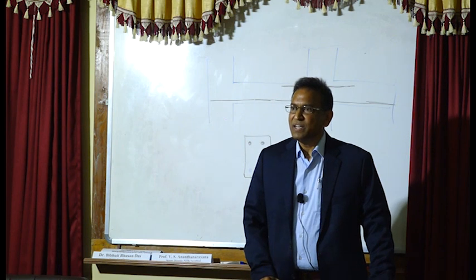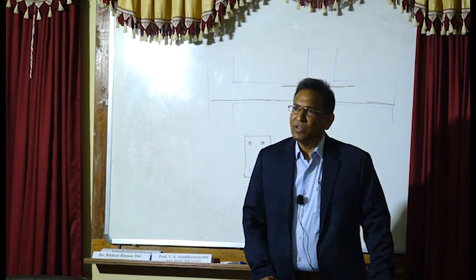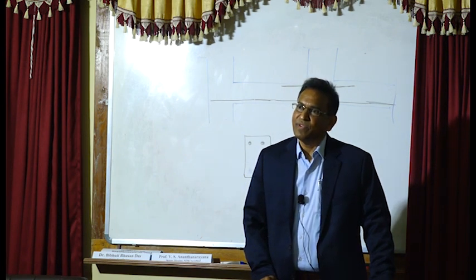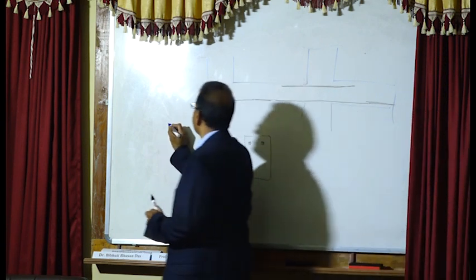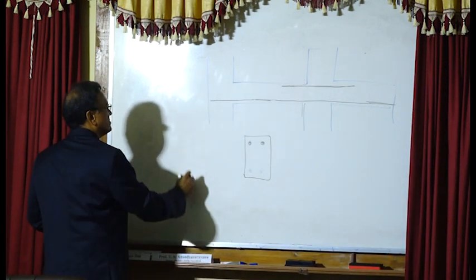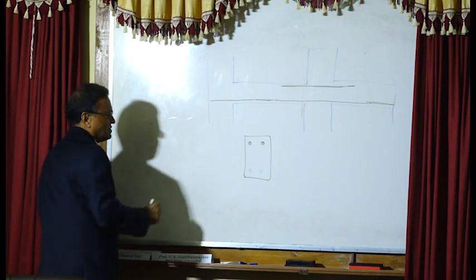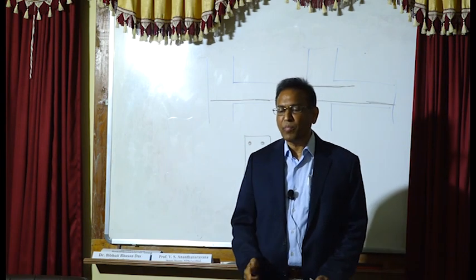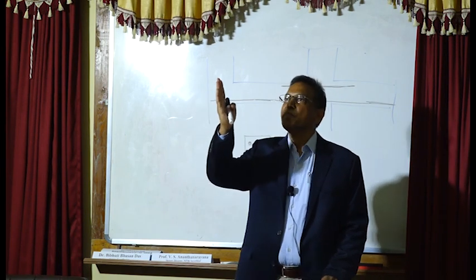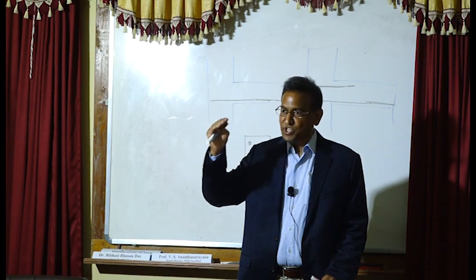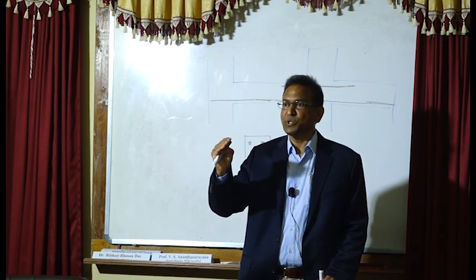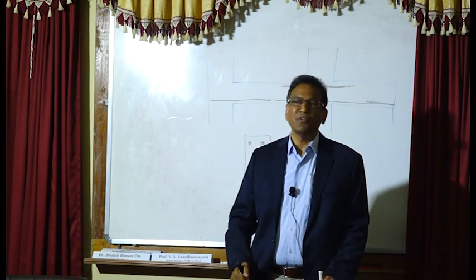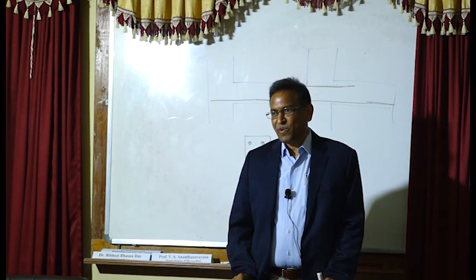This is the minimum reinforcement in the bottom part, and the maximum we are providing in the tension zone. So it is very strong in tension. I am not talking about this part. I am talking about columns. If you observe the PM interaction curve, then we will observe the bending moment dominancy zone. When the bars are below the neutral axis and going in tension, you can use them, or you should use them. But if they are in the compression zone, you will not use them. You know what I mean?